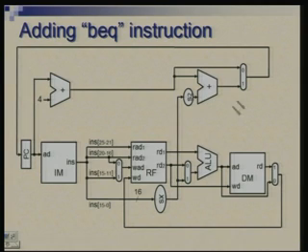So now let us look carefully. First of all, this is a multiplexer which is making a choice. Either we take PC plus 4, or we take the output of this adder, which is adding something to PC plus 4. What is it we are adding? We are adding this 16-bit constant which has been sign extended, but it has also been shifted. This S2 I am using to shift this number by 2 bits to the left, which is effectively multiplying by 4 and getting a byte number from word number.